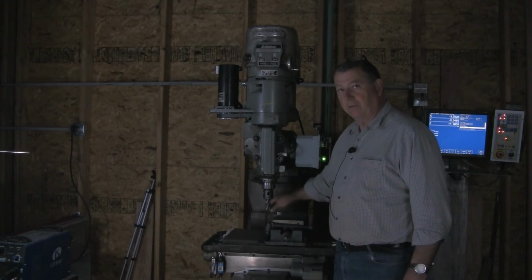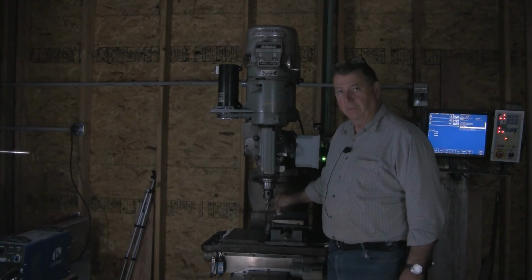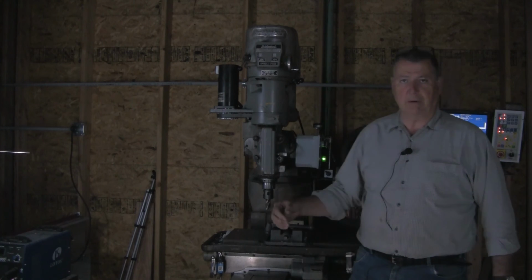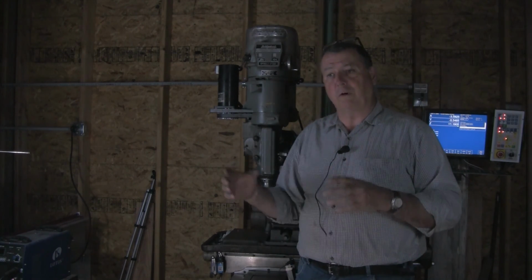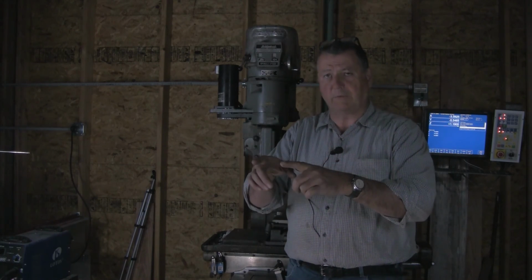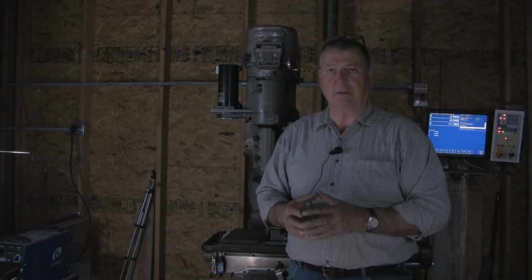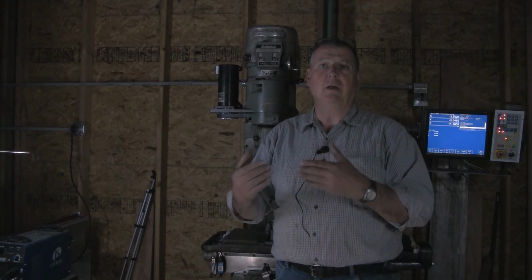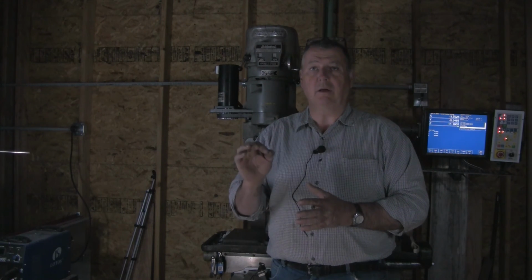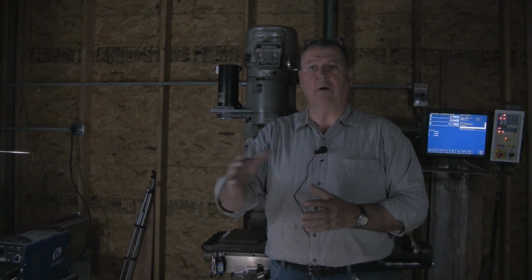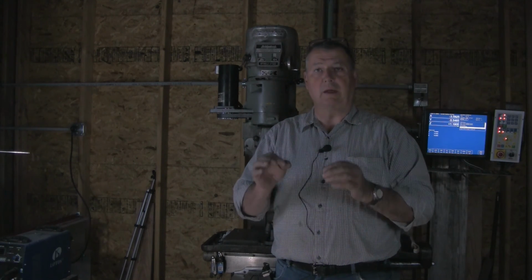All I have to do is make sure that it's aligned with my fixture, type in the G55 command or add that to the beginning of a cut file, G55, it will then go from its machine coordinates to that specified location and begin the cut process. And I don't have to go through the entire time of setting up and edge finding each and every time I put a part in there. So that's why it's so important to have a steady, repeatable home position on your machine. It allows you to then work from offsets anywhere on that machine, and they will always be precisely the same.